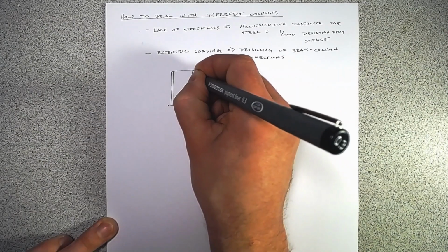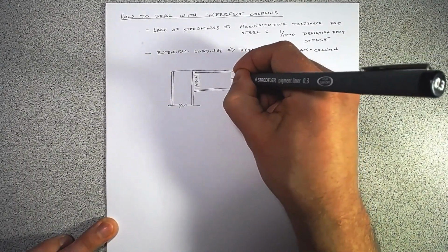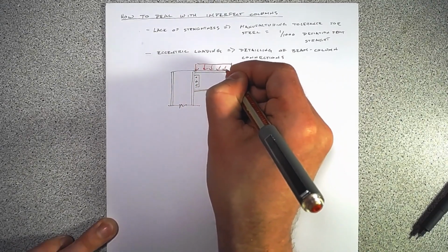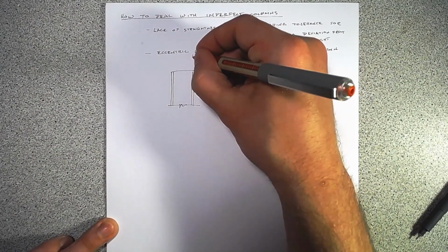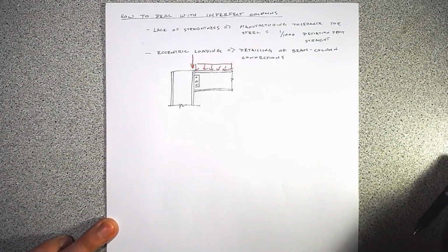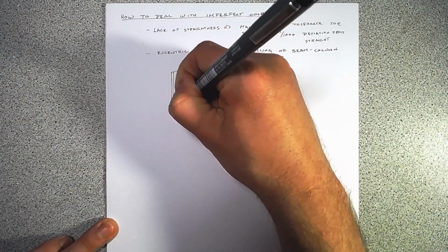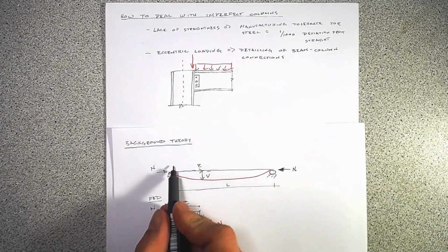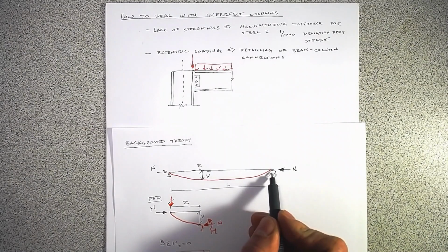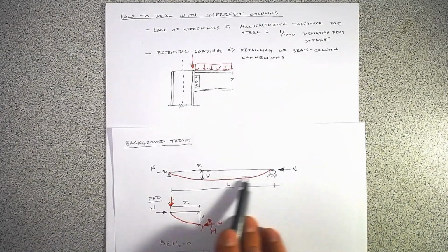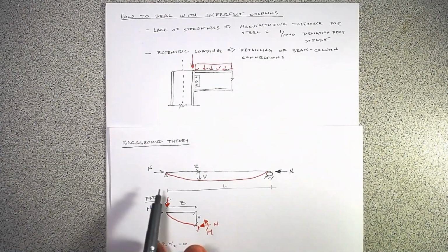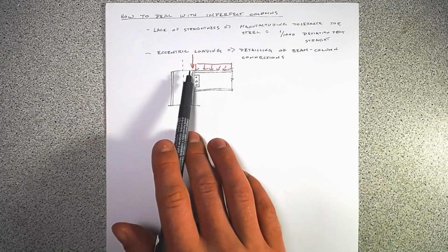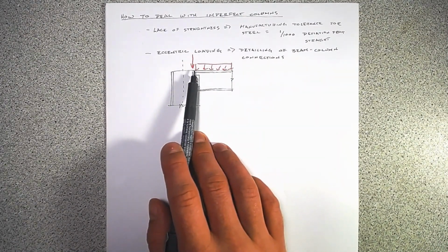And even if that beam is just, say, connected through a web plate, but it has some loading on the top, well, the resultant load is going to come in off center line of our column. And if you think about it, our Euler buckling is all based upon center line of the member. So you could draw a member in here. This is the center line. This is what we're looking at, because the center line is where the line of action will be for the internal stress, which is going to be resisting this external force. So we also need to deal with this type of eccentricity.